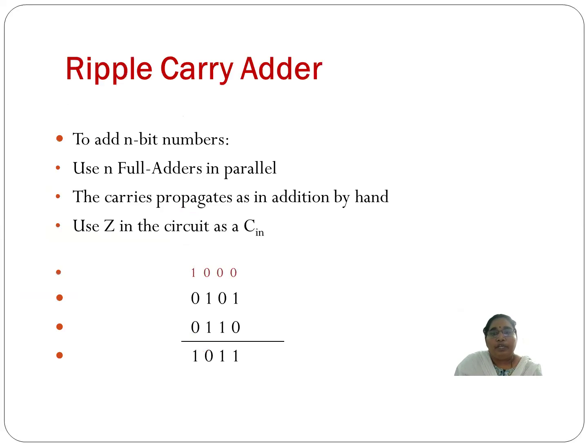So that is why we go for addition using another method called ripple carry addition. To achieve the same addition, we will use full adders instead of the normal design practice of a combinational circuit. To add n-bit numbers, we just need n full adders.